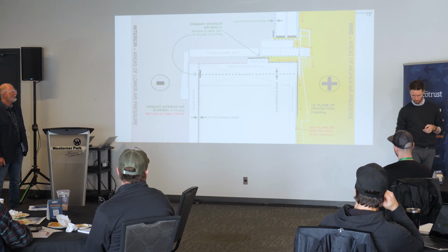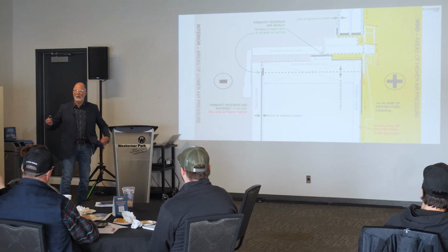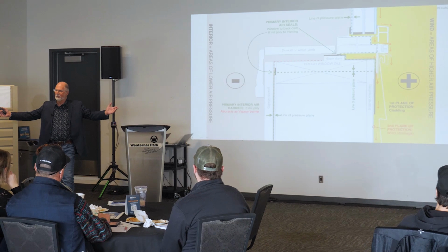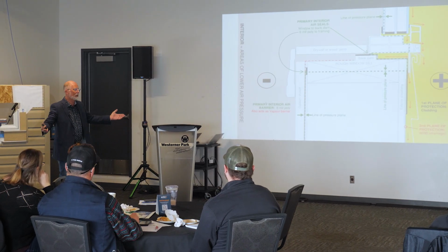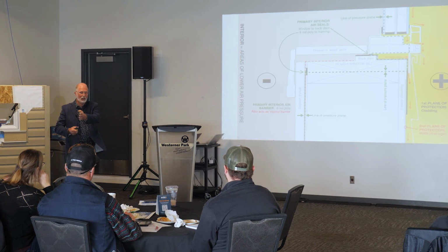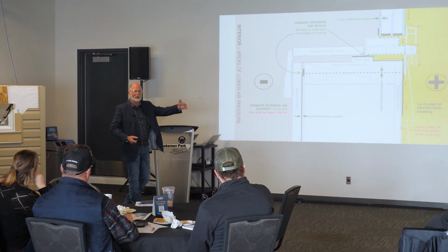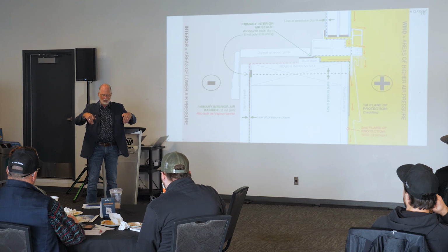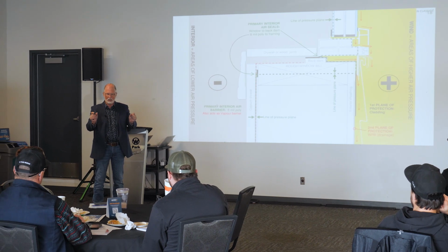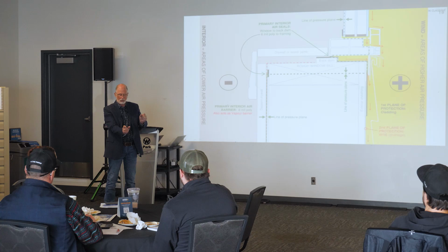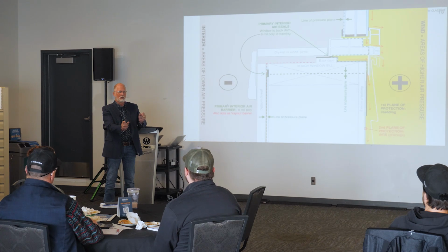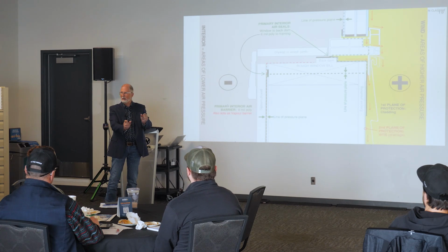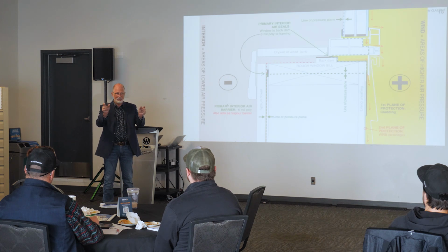Yeah, exactly. And think about a window installation. You put a giant PVC window in. What's the structural ability of a PVC window, right? And you've got setting blocks in there somewhere, supporting the glazing, which transfers the load to the PVC. So you have a setting block here, setting block here. The framer puts a block for support here between the two. And that 600-pound window over the next 5 years starts to sag.